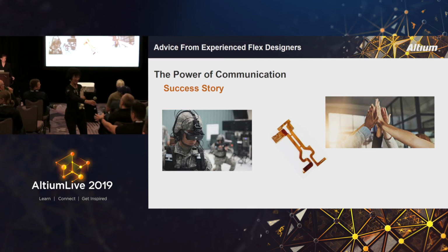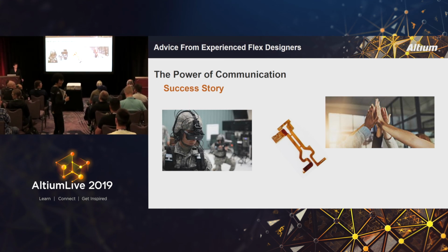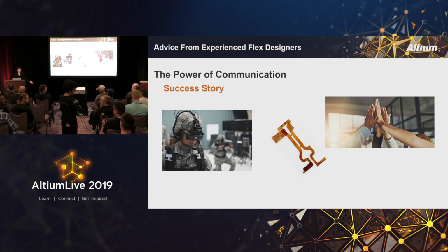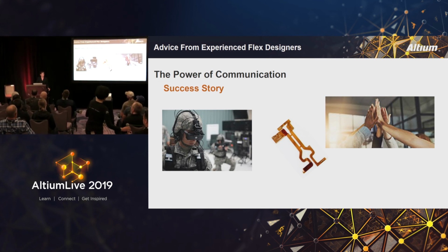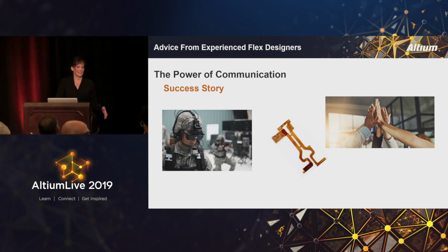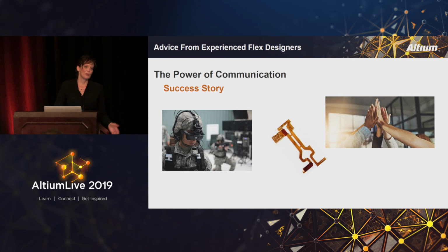Sorry if this is a silly question, but what are coupons? Oh, so on the edge of the panel, they're used for testing all the different attributes. So IPC class 2, IPC class 3. They simulate the board. Connectivity, yep.